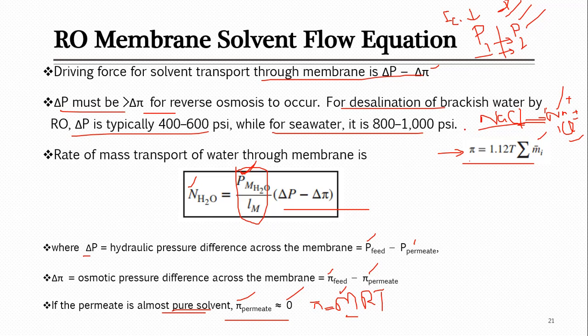again the same. But for example you have CaCl2, in this case the number of moles of Cl is double as compared to the calcium. So when you calculate the molarity for calcium and for chlorine, you have to add them up. So overall this equation can be used for calculating osmotic pressure on both sides of the membrane, on the feed side as well as the permeate side. And we will use this in one of the problems we have to solve at the end of this lecture, so you can see the utilization of this equation.